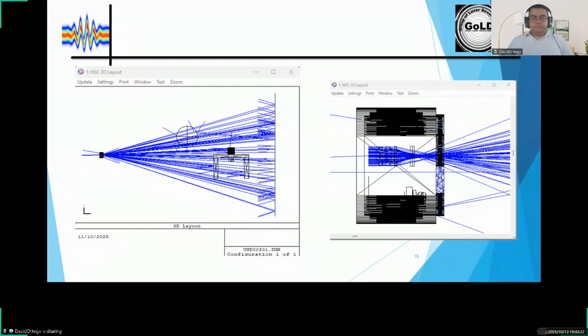There's another software, but we need to use SolidWorks from the 2012 version. That is the PartLink. PartLink is when you use a DLL so that ZEMAX and SolidWorks communicate at the same time. If you modify one piece in SolidWorks, it automatically links this modification into ZEMAX, and maybe then I can do that operation because it's very useful. In the newer version, we cannot do that. The PartLink was removed.